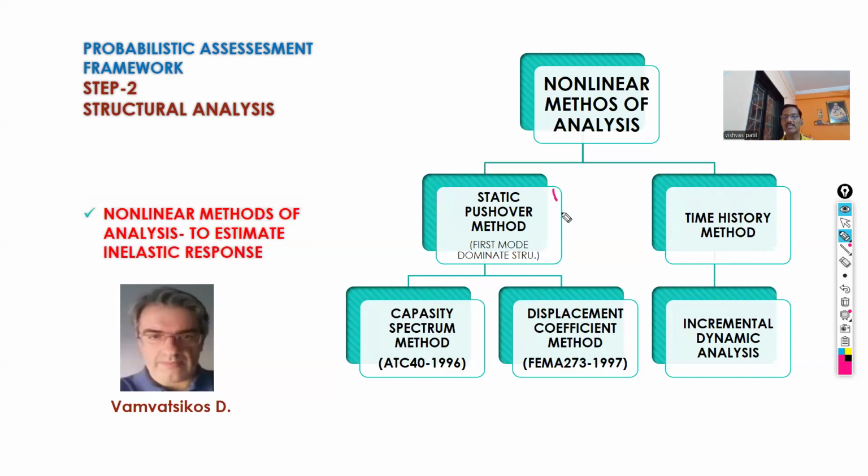There are two methods traditionally. First is known as the static pushover method, and second is the time history method. In the static pushover method, the structure is pushed on one side until failure. While pushing, we apply lateral force, that is, earthquake-induced lateral forces are applied on the structure. Therefore the structure will undergo different stages up to the failure. That is the simple principle of static pushover.